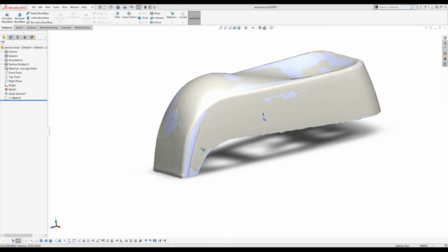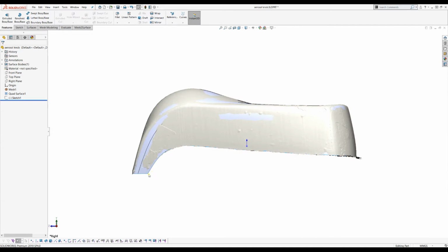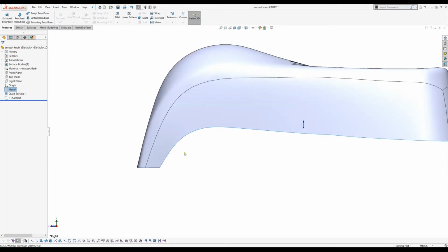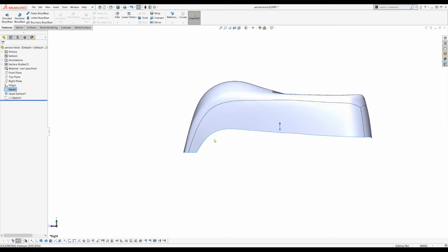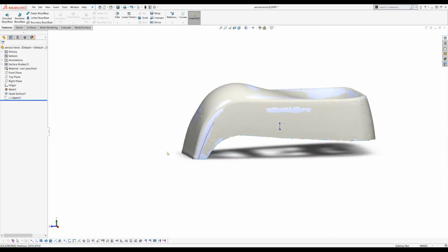So far we managed to reconstruct this shape here, and if I put the object on the side, you see that I managed to reconstruct this surface. I'll just hide the mesh, and this looks okay, but because of the freeform, probably this is not what I want. What I mean with this is that the best approach is maybe to create a sketch like this one so that I can define my precise exact cut through this object, and I want to reconstruct the bottom in a more precise way where my sketch will actually be the guiding one.